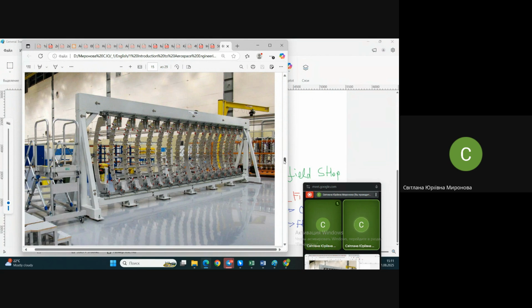However well you produce the parts, they will find a way to spoil themselves just on the way to the next shop. They may bend under their own weight, even if you place them in a supportive device. This technique doesn't work practically. It works only for massive parts. For instance, for landing gear, it may work. For elements of the fuel system, some pipes, pumps, hydro cylinders, it works very well. For manufacturing of brackets, some massive parts, it works very well, but not for airframe parts, which typically look like eggshells, you do remember, or like strings.